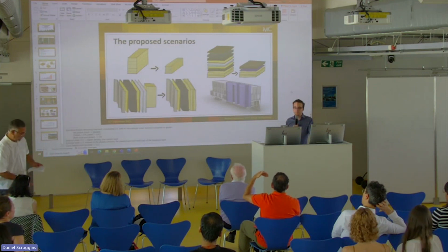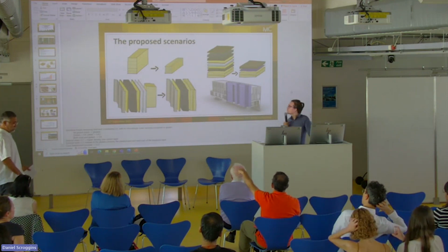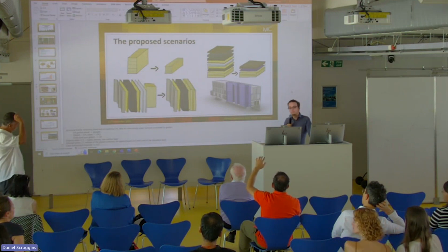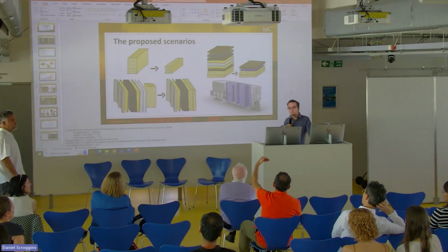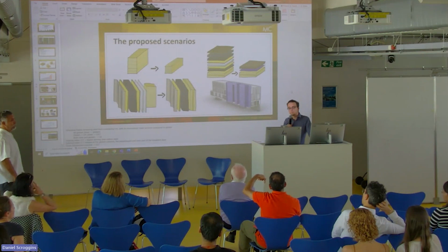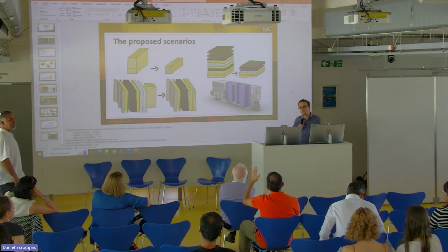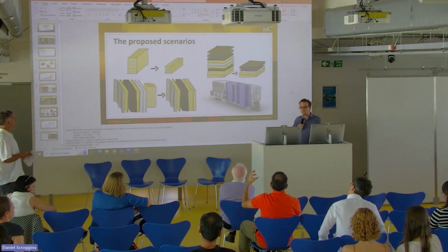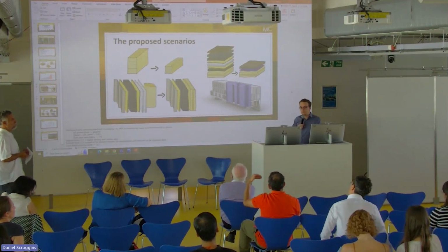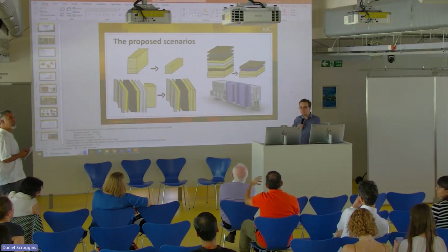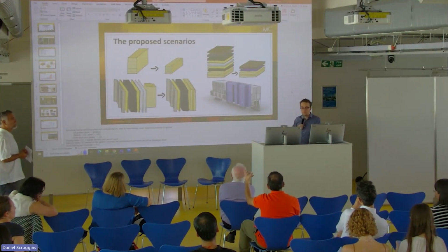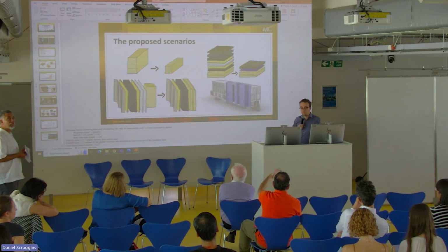Once you're doing the overall lifespan calculation for the energy, did you think of doing the study for the effect that timber could have on the internal thermal behavior? Timber could be considered a material which is in between. It could be considered lightweight, or it could be considered heavyweight and thermal mass. So it could have an effect on improving the excess heat. Have you thought about that, or would you think of pushing it more to study the thermal effect of the timber and thus reducing the cooling effect if needed?